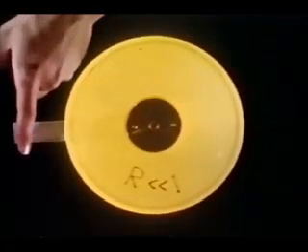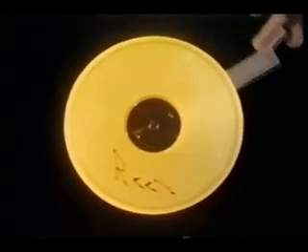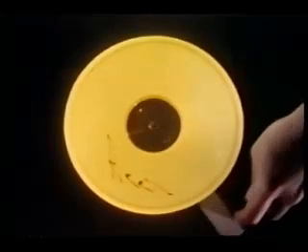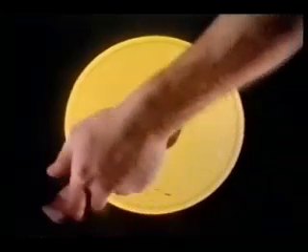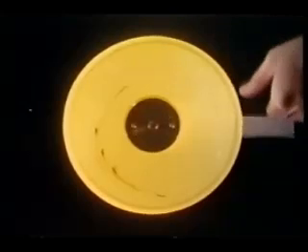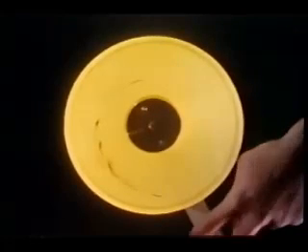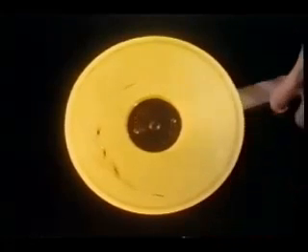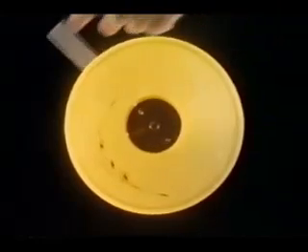During the forward motion, the boundary of the fluid follows a path determined at each instant by the motion of the wall. At these very low Reynolds numbers, particles within the fluid move when the boundary moves and they stop when it stops. During the reversed motion, the boundary of the fluid returns to its original position.